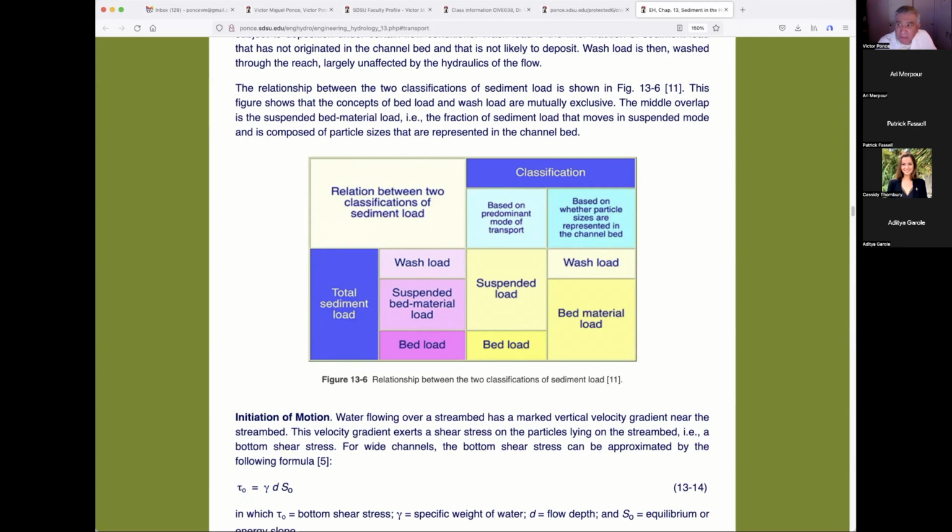And when I say sand bed channel, I stress that because sand bed channels are the ones that we engineers typically look into and calculate, because it's required. Many of the rivers that we study are in the valleys, and in the valleys, the bed is composed of sand. If we move upstream, the bed may have some gravel. As a matter of fact, upstream in the mountains, there are some gravel beds that don't have any sand for that matter.